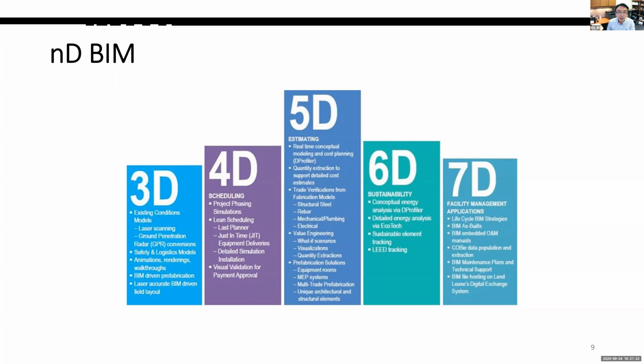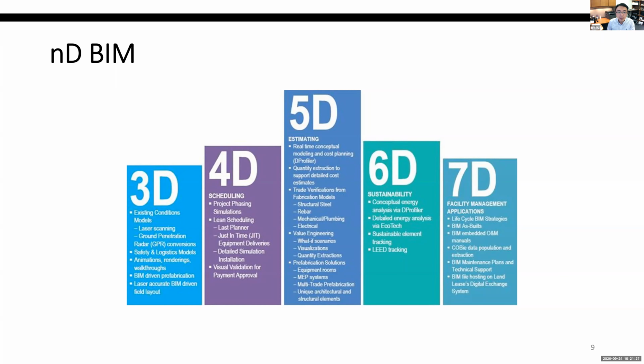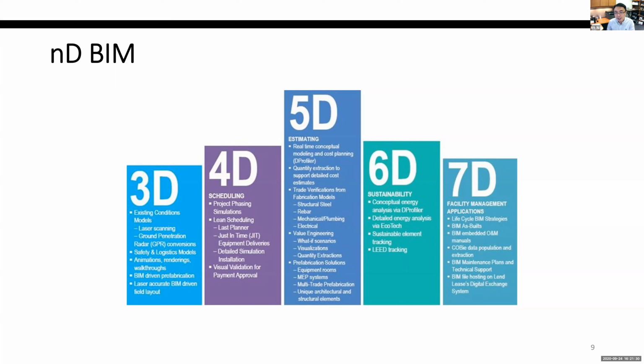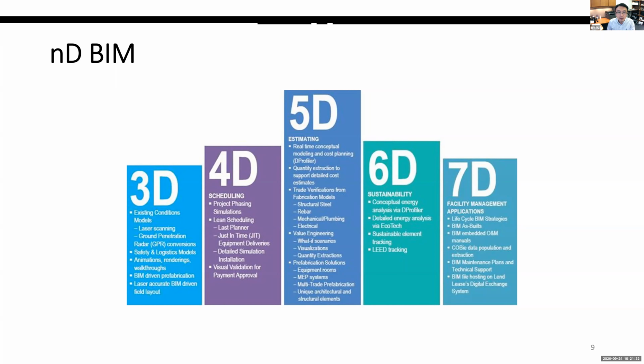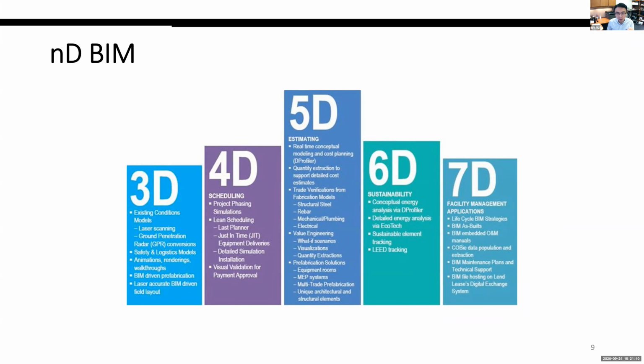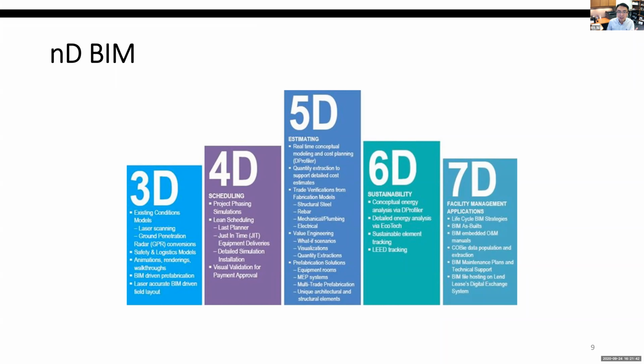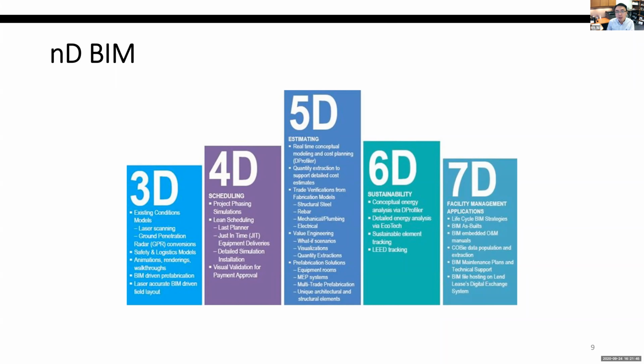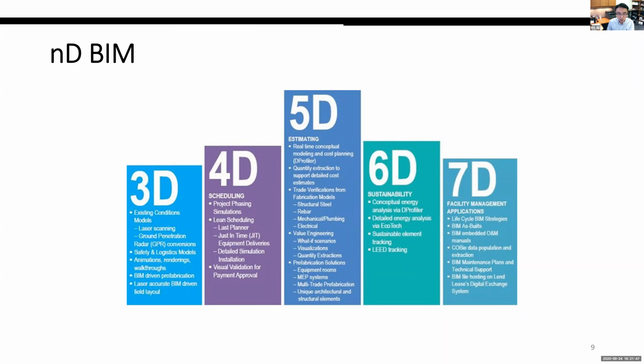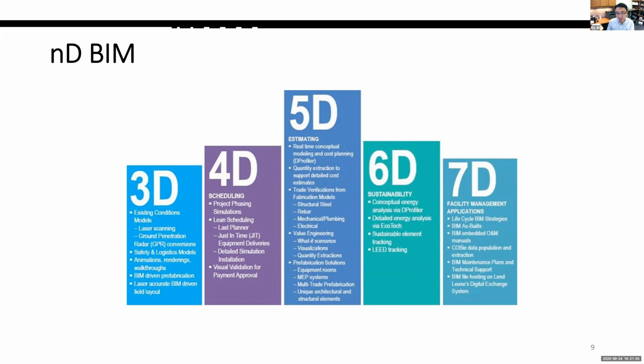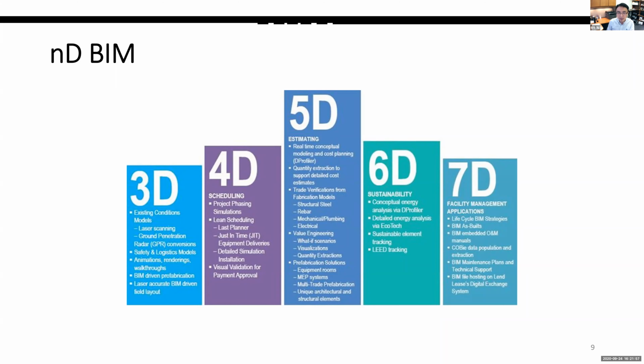So for the 3D BIM, let's say that's the beginning part of BIM. We basically store the geometry information, the relationship information. And the 4D BIM means we add time information to that. So for example, if you open the property window of a concrete pad, that view basically shows you how long it will need to pour the concrete pad. So that's time information. And we call this kind of BIM model 4D BIM. And this kind of application is called a 4D BIM application.